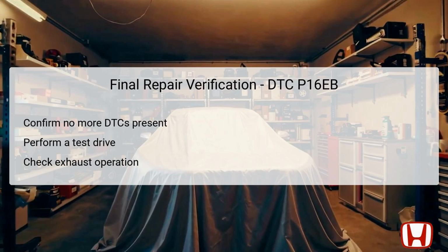Following this, a test drive is imperative to validate that everything operates effectively under real driving conditions. Pay careful attention to the exhaust system's behavior during acceleration and deceleration phases. In particular, make sure the active exhaust valve operates smoothly. Any irrational responses or further issues should be addressed immediately to ensure the vehicle's performance is restored to optimal levels.